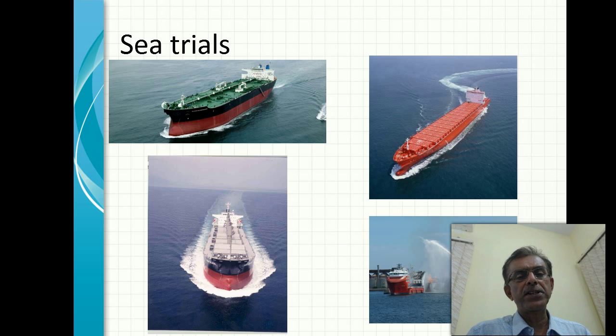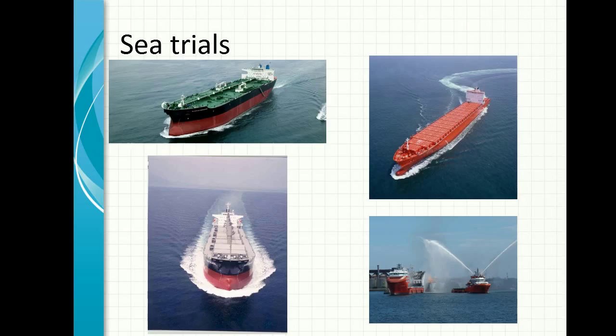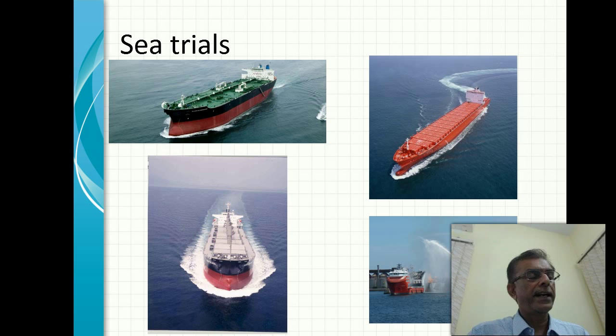These are just some pictures of maybe a speed trial of a new ship. This could be a zigzag maneuver. This could be a turning trial. There could be other trials. For example, what you're seeing here is an offshore vessel with the firefighting systems on, and with that you may do a maneuvering test. You may want to go nearer. These test protocols are defined beforehand, agreed on, and in a systematic manner the sea trials, which may last for a week, are conducted, and these measurements are recorded and available during the lifetime of the ship.